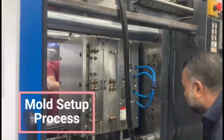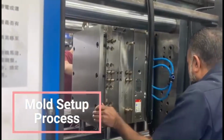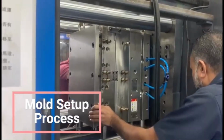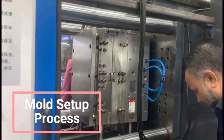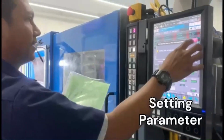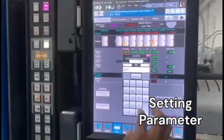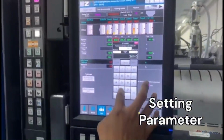Mold setup to machine refers to the process of installing and securing a mold onto a machine to produce parts. This involves aligning the mold, properly clamping it, and configuring machine settings for the specific molding process. The technician sets machine parameters, adjusting temperature, pressure, and cycle time for optimal performance.